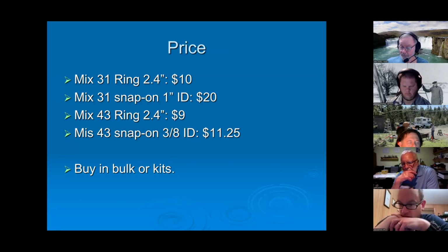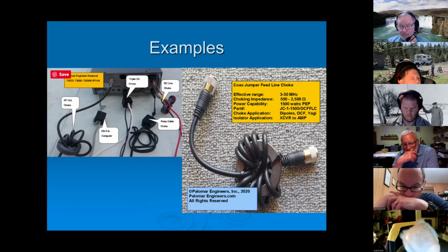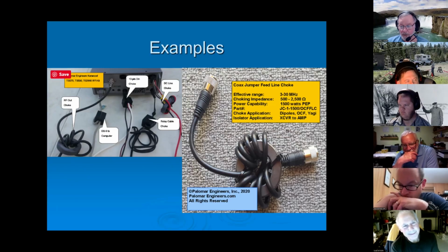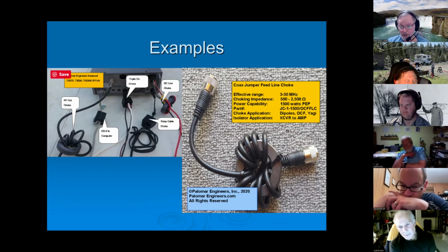Ted was asking a question here, and I had a similar question. On this choke, how does it impact the center conductor versus the outer conductor, as far as attenuation? It does not affect the center conductor. It only affects the outside of your coax. The outside of the coax is the one that's most commonly getting all of the interference that is traveling on it, not the center conductor. So the outer conductor is kind of protecting the inner one then. Yep.